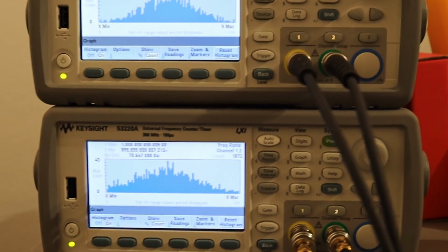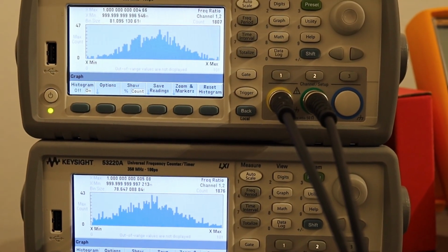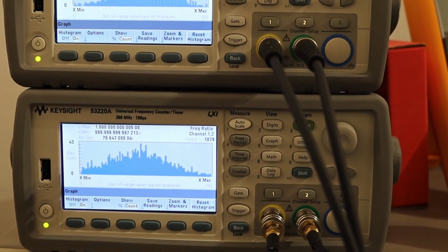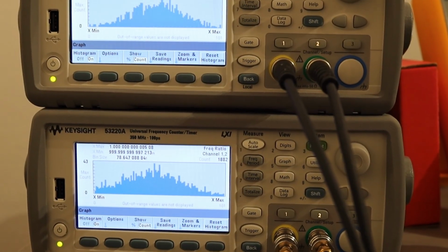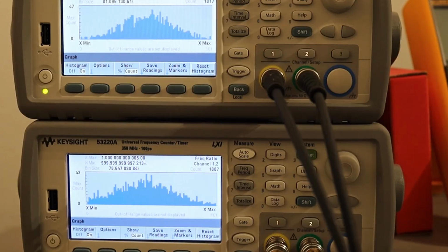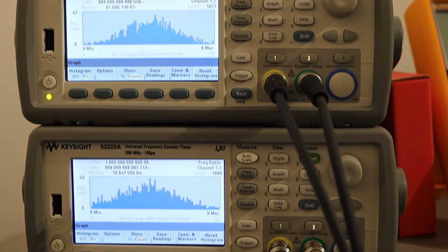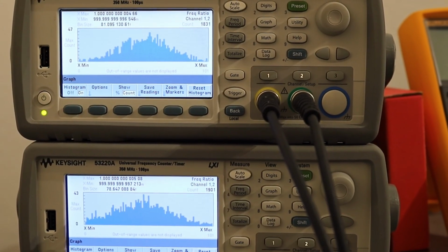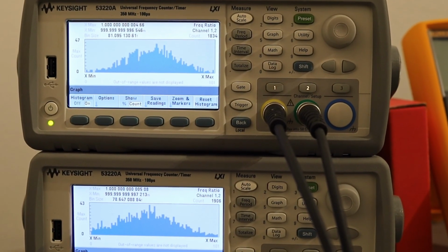So for 10 MHz, 82.27 pico of error in the ratio will result in an error of 82 microhertz, and of course on the bottom it will result in around 78 microhertz. So we have successfully verified that the output correlation between channel 1 and channel 2 is exactly the same as from one single channel. So my distribution amplifier is not causing any frequency deviation between two different channels. So it's performing very well.